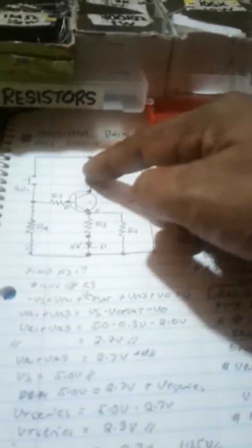So 5 volts minus 2.7, the voltage drop across the transistor and the diode, 5 volts minus 2.7 is equal to 2.3. That is the remaining voltage drop across here. We divide that into 2 for these 2 resistors. So 2.3 divided by 2 is equal to 1.15. Each has a voltage drop of 1.15 volts. We know the voltage drop across resistor 3. We now compute R3 using Ohm's law, my favorite magician. Voltage drop over current is 57.5 ohms. That is 100 ohms, my available resistor.